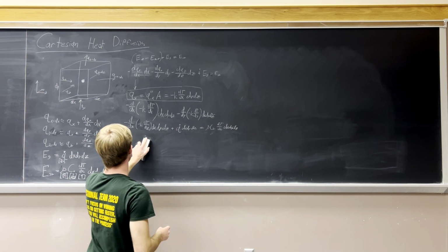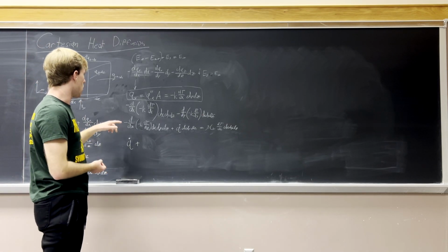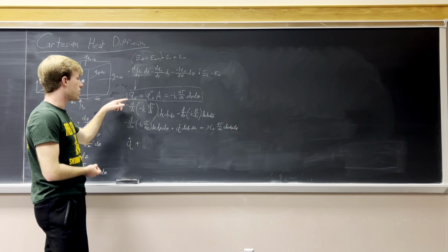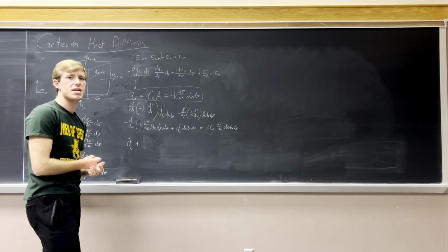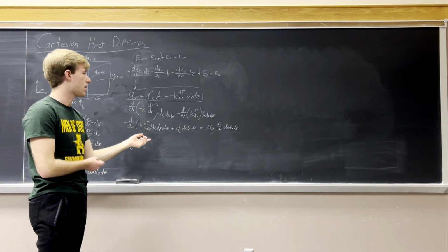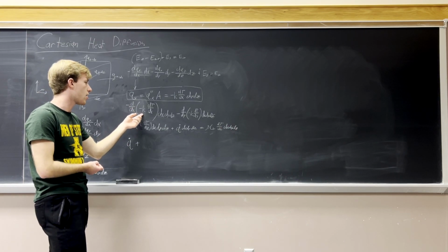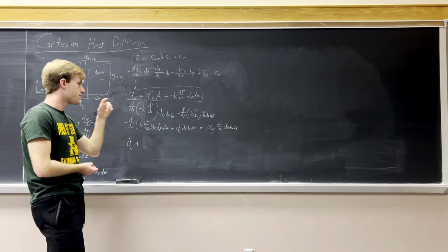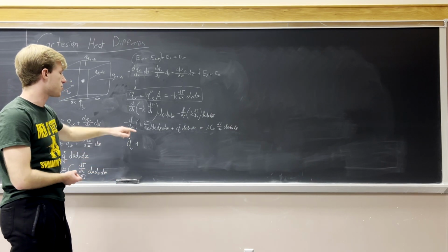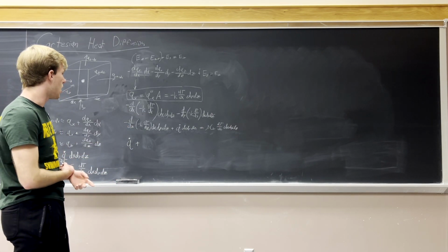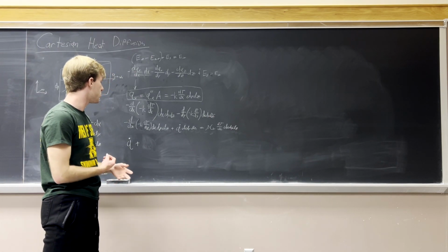Okay, actually, we can also just do this derivative anyway. So we'll do that while we're here. So if we look at this, we're changing over a specific area of x for both k and dT over dx. So our change in temperature over our length, and then we're looking at how that changes with respect to length. And same thing for k. How does our change in thermal conductivity change with respect to moving in x? And obviously, we don't know, because there's no guarantee that either of these two are constant, so we can just take the derivative of them with respect to x. So we're going to do that.